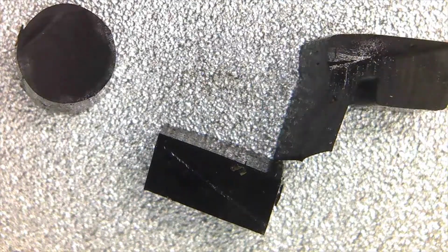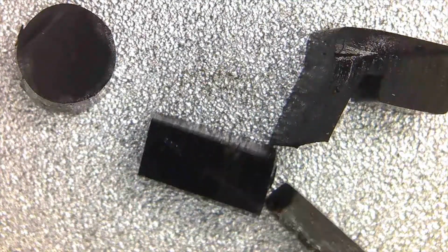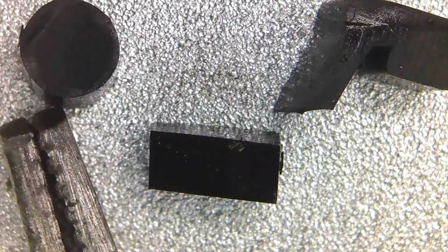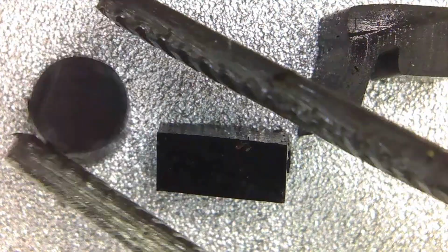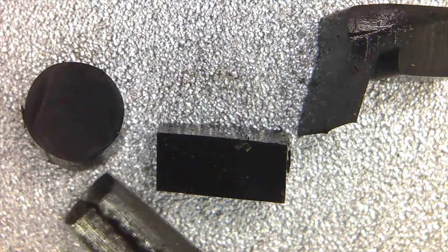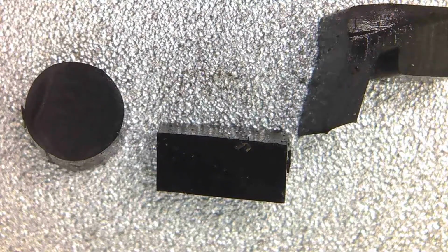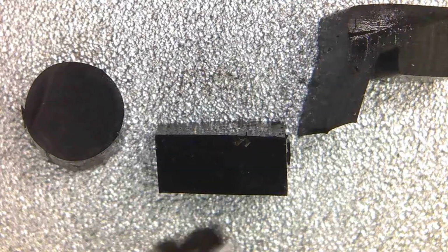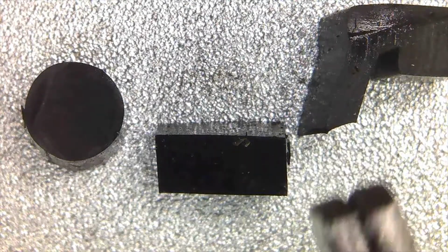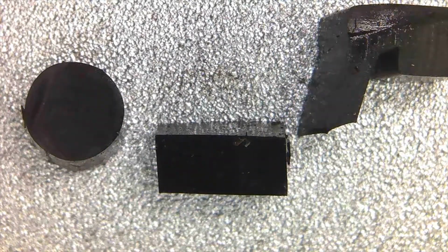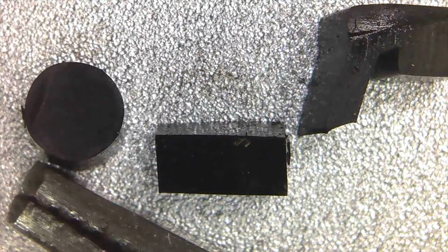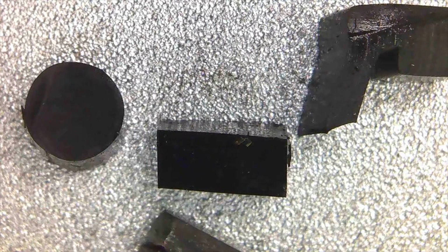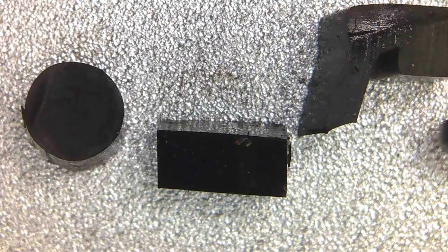Now we're over here at the microscope, and I've taken those pieces that I sectioned off of each one of those types of seals, and we see the first one here, which is the O-ring seal right there. You can see that it's literally just a round seal. And that's the shape of it all the way around the piston seal. The second type is the square cut seal here, and you can see it's not technically square, but it does have square corners, so they're each 90-degree corners of rubber. And of course, remember that the O-ring seal and the square cut seal are non-directional. They can be installed in either direction, upside down or right side up.